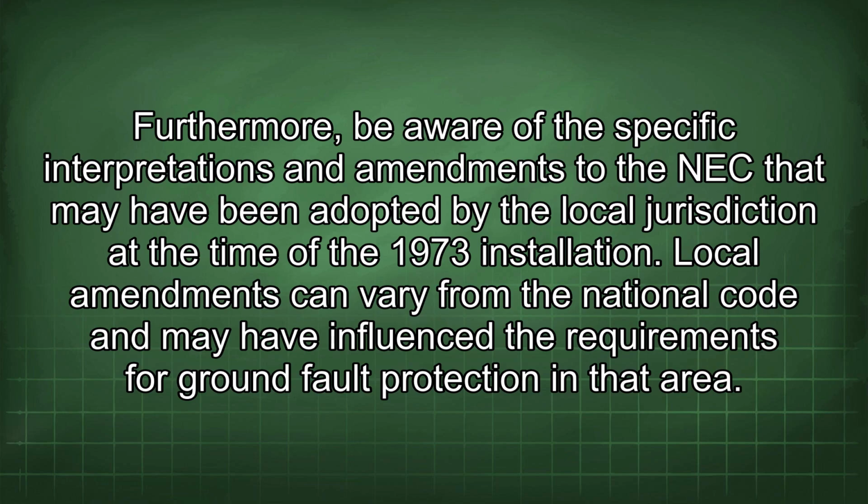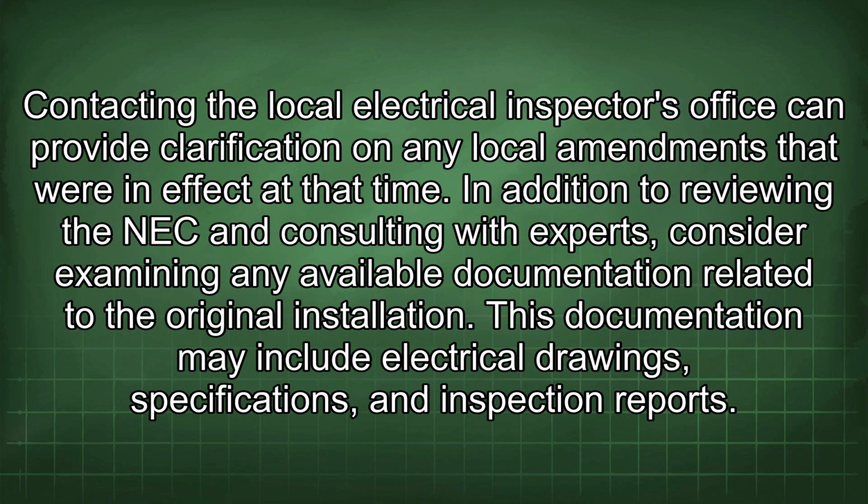Furthermore, be aware of the specific interpretations and amendments to the NEC that may have been adopted by the local jurisdiction at the time of the 1973 installation. Local amendments can vary from the national code and may have influenced the requirements for ground fault protection in that area. Contacting the local electrical inspector's office can provide clarification on any local amendments that were in effect at that